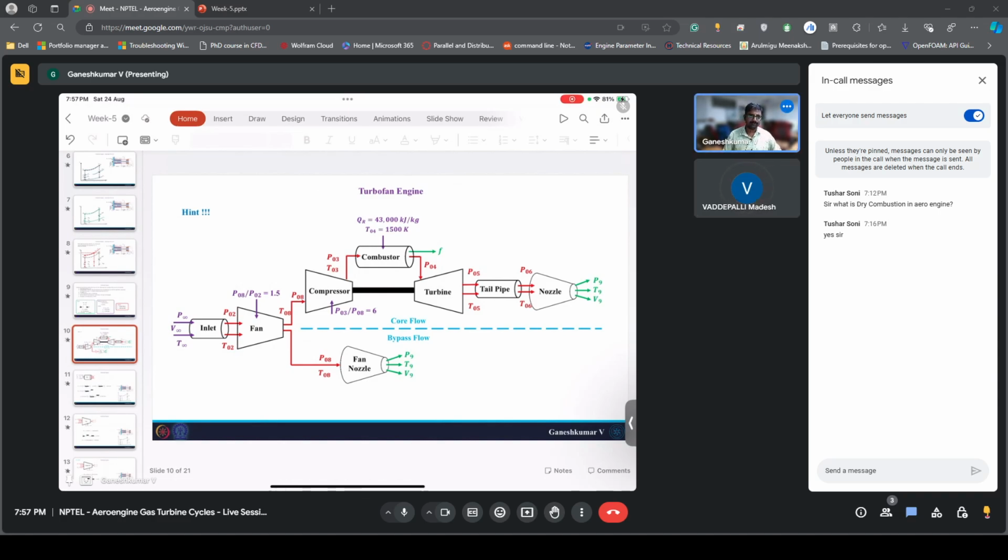Yes, actually this course is to design an engine, but from a thermodynamics perspective. So in terms of cycle design, basically, there are different components. There are different variables that you have encountered here, right? Something like pressure ratios, compressor pressure ratios. You have turbine entry temperatures. For a turbojet, these are the two design parameters.